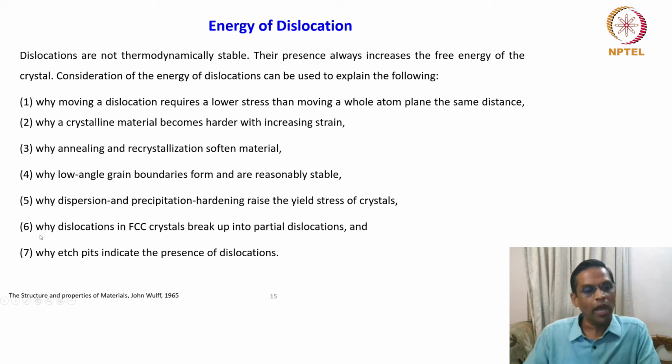And finally, why do dislocations in FCC crystals break up into partial dislocations, and why do etch pits indicate the presence of dislocations? We will see in the future slides that a dislocation can dissociate into two dislocations.